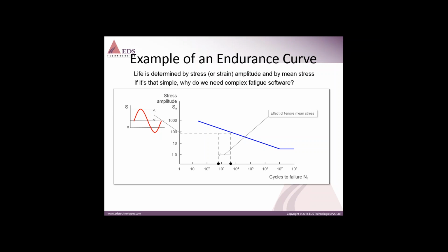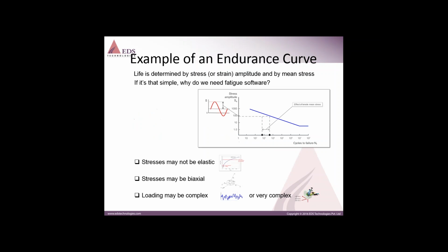So if it is that simple, why do we need complex fatigue softwares? Here's the answer. Stresses will not always be elastic in nature. This stress life curve or SN curve is designed keeping in mind that the stresses will be elastic and not plastic.